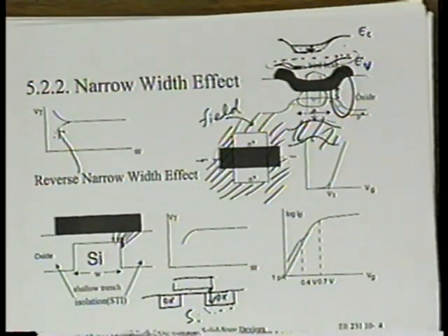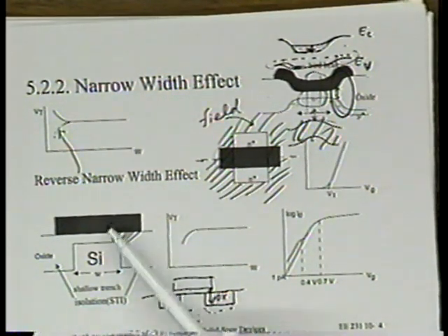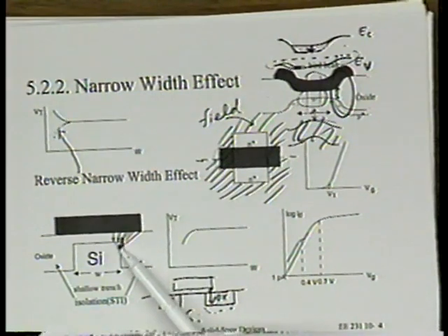By all means, if it doesn't help you, use your other intuition about electrostatics to explain to yourself why here you actually see a larger effective capacitance. But certainly, you don't even have to use that word capacitance. The key operative word is that for a given voltage, the electric field here is larger in the corner than in the center of the channel. That you probably can see just by thinking of this as a lightning rod. The electric field is larger.